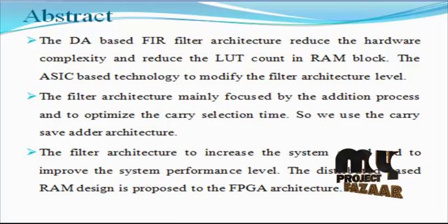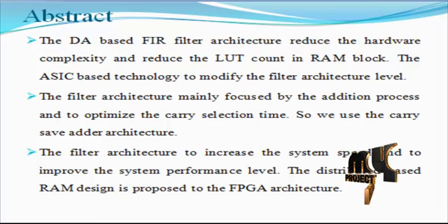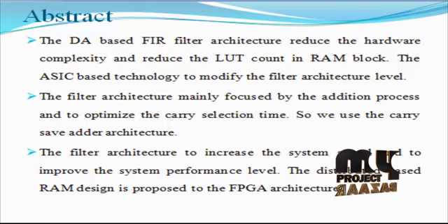On the other hand, a general multiplier based structure requires a large chip area, consequently enforcing a limitation on the maximum possible order of the filter that can be realized for high throughput applications. The brief presents an efficient distributed arithmetic based approach for the high throughput reconfigurable implementation of finite impulse response filters whose filter coefficients change during runtime.